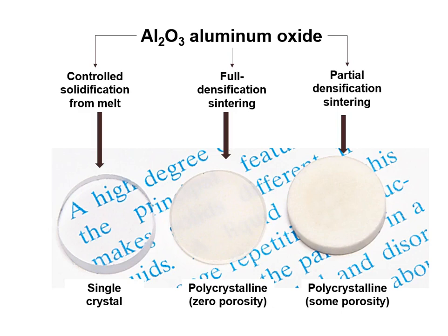If you get rid of all those voids, you attain a certain amount of translucence, and you see that in the middle. Well, you do that by the same process that you started sintering with, but you just continue it. You continue to densify the structure, adding heat, adding pressure, eliminating high surface energy surfaces until all you have are aluminum oxide grains impinging on each other. So you now have one phase, but you have a lot of grain boundaries. All of those aluminum oxide crystals aren't lined up in the same direction, and so the light can bounce off the grain boundaries. This is a multi-grain structure. It's translucent, not transparent. Much better fracture toughness.